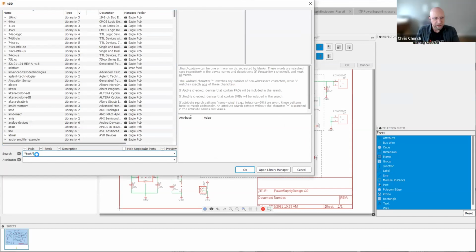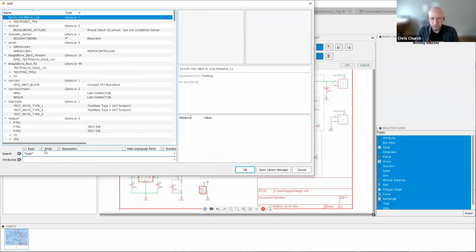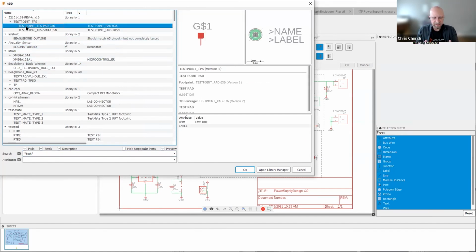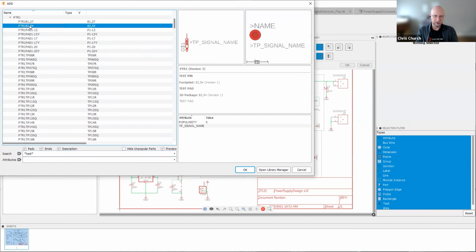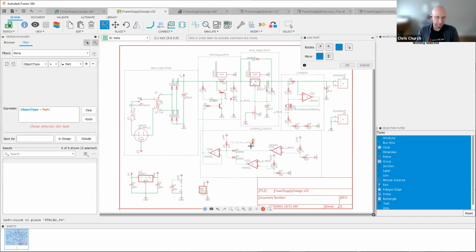So while you're doing that, I'm going to answer a couple questions. One of them that came in is, at what quantities does the test fixture and final assembly become cost effective? It is going to depend on the design. If we're talking about a very expensive BOM, a very expensive design for the PCB assembly, adding a minute or two of labor for the testing may not be a big deal.